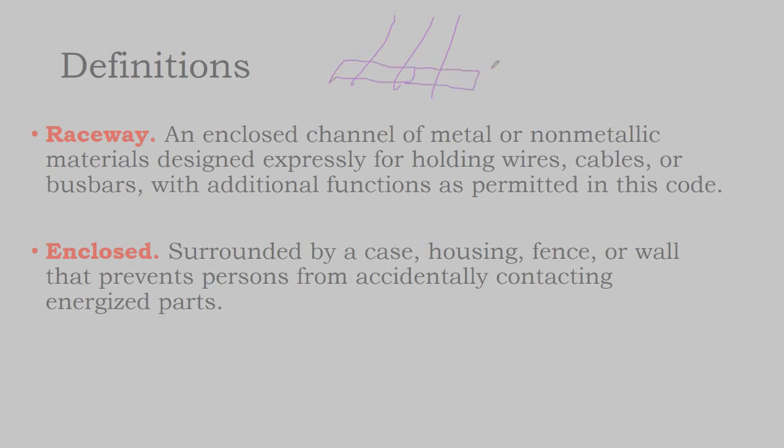That's pretty nice because that's nice and well insulated as far as the interior of your building. So here's your rafters, and you're putting down your glass on glass modules, and you're using like butyl skyscraper glue to seal the glass together. And that's something that a building framer will be better suited to do. So here's your rafter. Here's your solar panel.